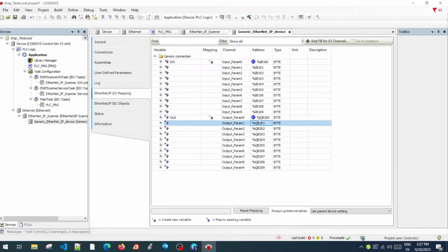I have a question, go ahead. Sorry, no. Is it only possible to do this addressing in bytes in Codesys, or can you also do words? Then it's completely easy to map it. No, this is the default one. So it's in bytes. It's the default one. Yeah. Okay. Then you need to. Yeah. The thing is that you know that IW50 is going to be this one. So if you want to take the entire word, then you can do it that way. Yeah. But that is what we meant with the previous slide, that you need to consider that the addressing is a bit different.